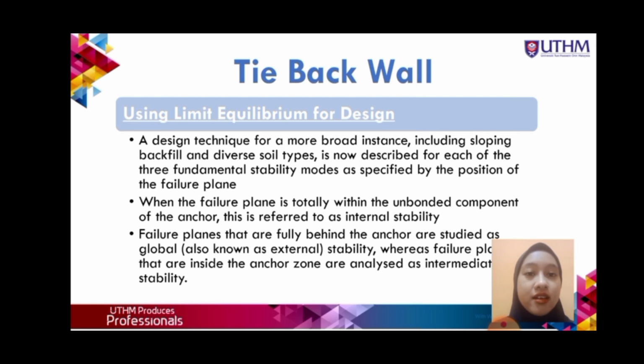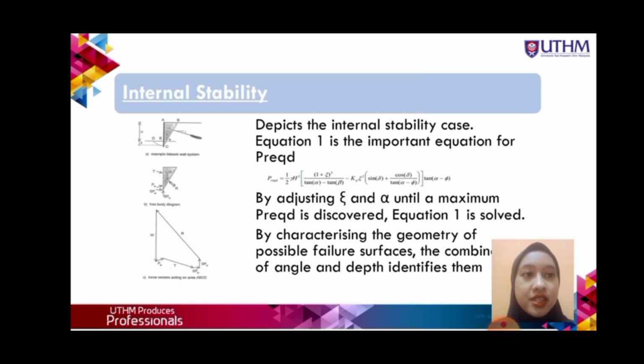The next is tie back wall technique. So we are using limit equilibrium for design. A design technique for a more general instance including sloping backfill and layered soil types. When the failure plane is totally within the anchored component of the anchor, this is referred to as internal stability. Failure planes that are fully behind the anchor are studied as external, whereas failure planes that are inside the anchor are analyzed as intermediate stability.